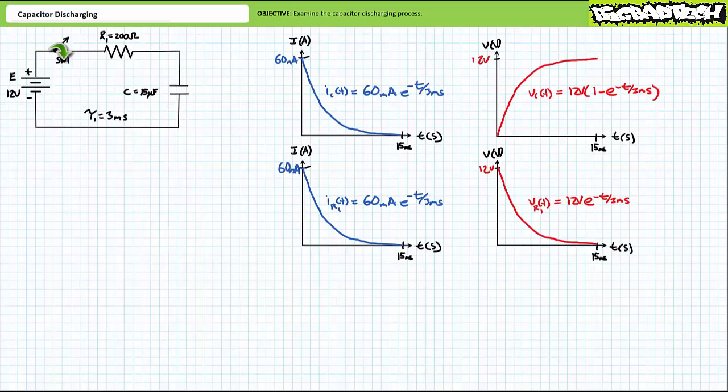Beyond 5 time constants, this capacitor will be as charged as it ever is going to get, and you cannot charge it anymore. If we open switch 1 after 15 milliseconds, assuming the capacitor to be ideal and exhibiting no self-discharge, it would still appear as if it were a 12-volt differential across the capacitor, positive to negative, top to bottom. The fully charged capacitor is in effect a reservoir of stored energy, albeit one of limited quantity.